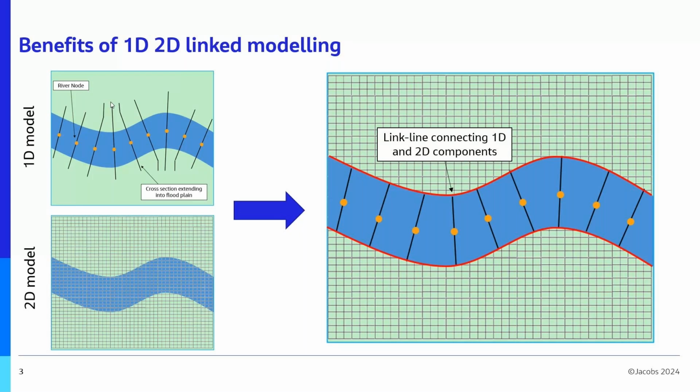A 2D model provides us with floodplain hydraulics. So results from a 2D model will give us water levels and flows at each grid cell within a defined active area at each time step. A 2D model is much better at representing the floodplain than a 1D model, as the results can show flow direction. To note, a 2D only model can be used for modelling in-channel flows, but often aren't, because the raster ground survey data in these areas is a lot less available.